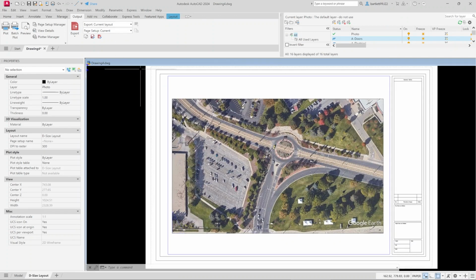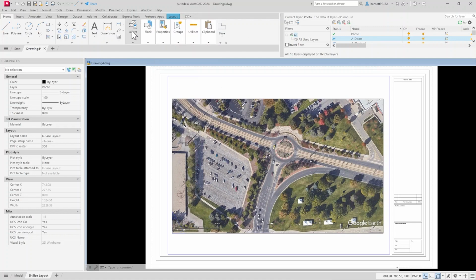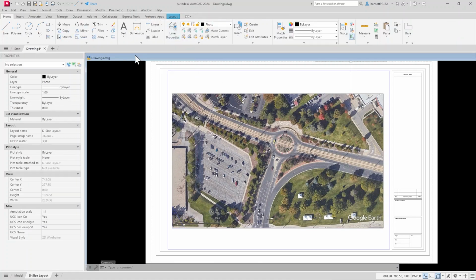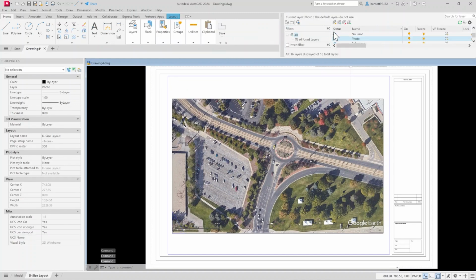One last thing to remind you about is if you look at the instructions on page 1, for each of the different features you draw, you're going to have to create a separate layer. So remember, you can create your layers by using this. Let me show you how I got there. Go to the Home tab again, go to Layers, and Layer Properties, and it opens up this menu, and you can create new layers by clicking here. So you want to name each layer differently, and I've told you what color of line you should be drawing on each of these layers.